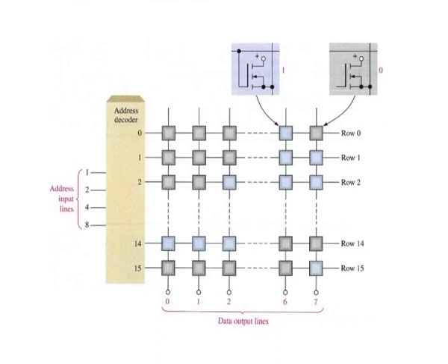For example, the ROM in figure is organized into 16 addresses, each of which stores 8 data bits. Thus, it is a 16 by 8 ROM and its total capacity is 128 bits or 16 bytes. ROMs can be used as lookup tables for code conversions and logic function generation.